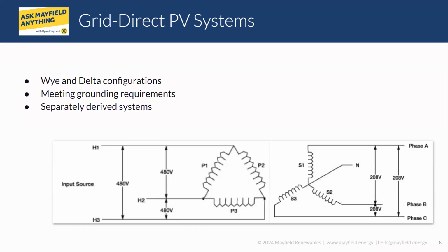So it isolates the two systems there. The term isolation transformer is confused a lot of times on what that really means. An autotransformer is basically straight through windings, and based on where it's tapped off, you'll have a voltage change, but there's no isolation there. So the current limiting function and the protection is not really there.